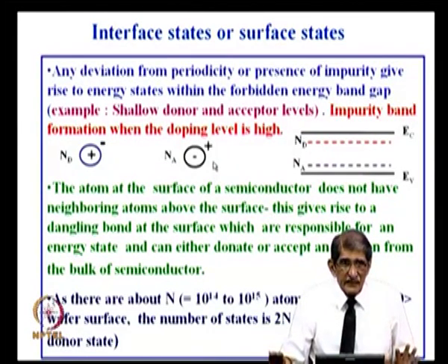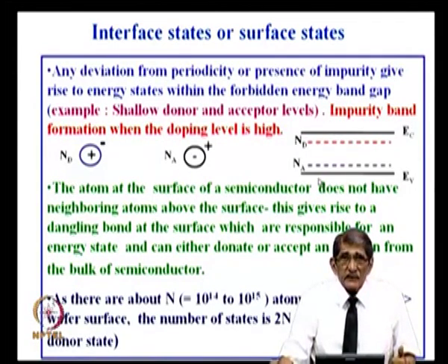To put it once more, if the electron is occupying the donor level, it is neutral. If the electron is occupying the acceptor level, it is negatively charged, because the plus charge is not there. Okay? That is the thing to understand the interface state density and its impact. Now, these are the shallow donor and shallow acceptor, implying very small energies are required for interaction between the donor level and conduction band and the acceptor level and the valence band.